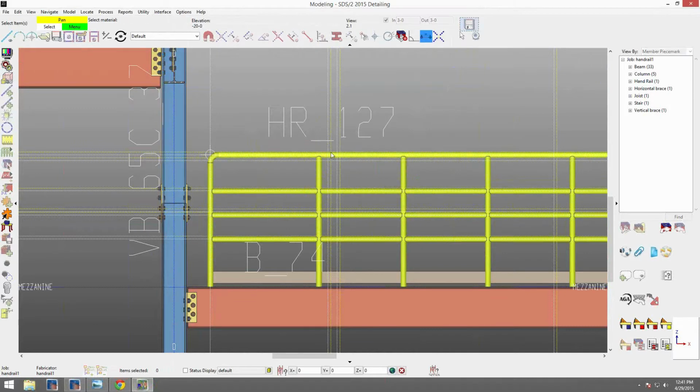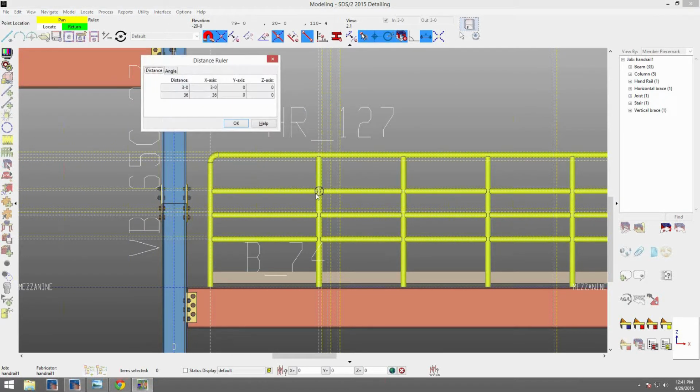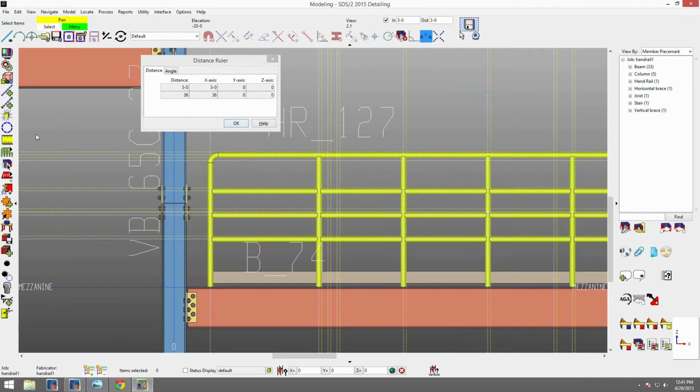So now if I do the construction line, add material again and measure from the center to the center, that's at 3 foot. And then it's saying again my maximum spacing, I would need a construction line, add material here. Said the maximum it could be for it would be 3'6", and it's putting at 2'4", so it's letting the system decide that.